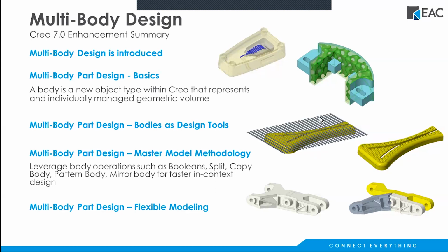And you can actually categorize these bodies as a construction feature. So Creo recognizes it as a separate body, but because it's a construction body, it won't show up in a bill of material, right? It's sort of like a skeleton part in a way. It's used to construct the main stuff, so we don't need it to be included with the main stuff.